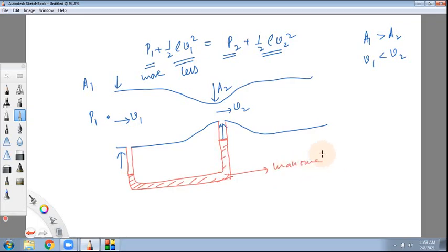A simple U-shaped tube in which you have certain other liquid. The pressure that you are measuring on this side is nothing but P1. This is what we call the static pressure. Because in Bernoulli there are three terms: P1 plus rho GH plus half rho V1 square. Here we are not writing that rho GH term because it is a horizontal tube. So at point 1 and point 2, at both areas of cross section, the rho GH term will be the same, so that gets cancelled. So the pressure we are measuring here is P1, and the pressure here is P2.